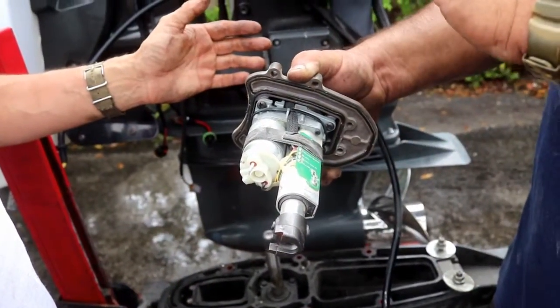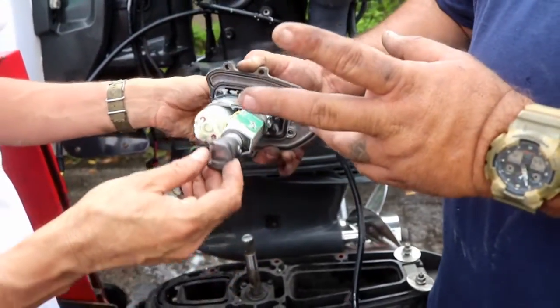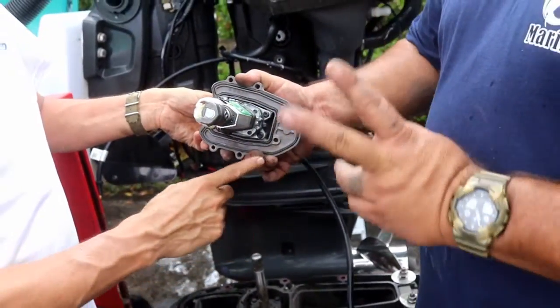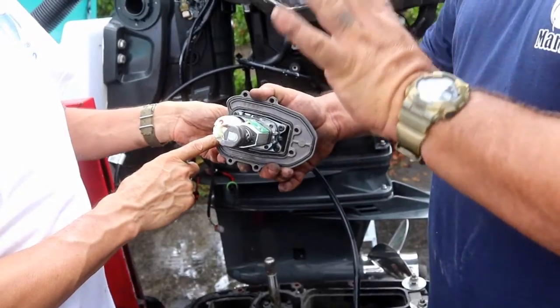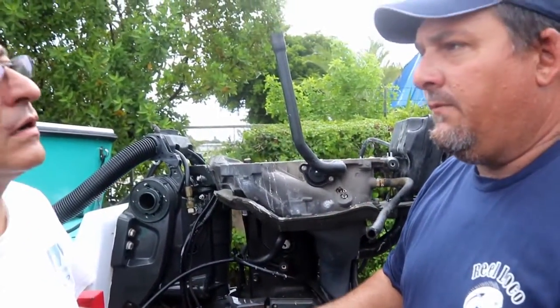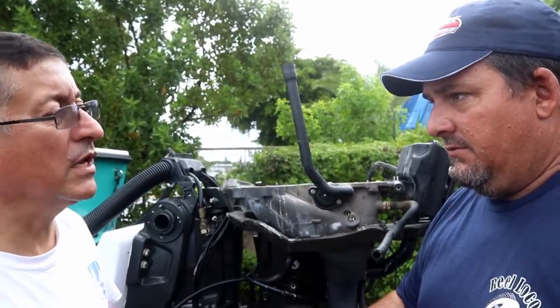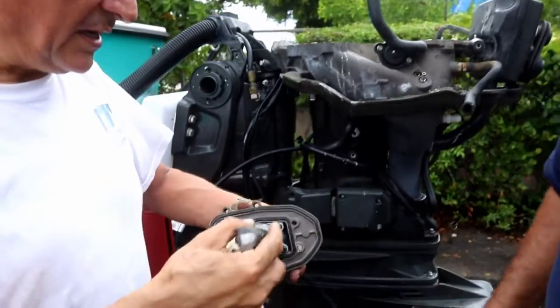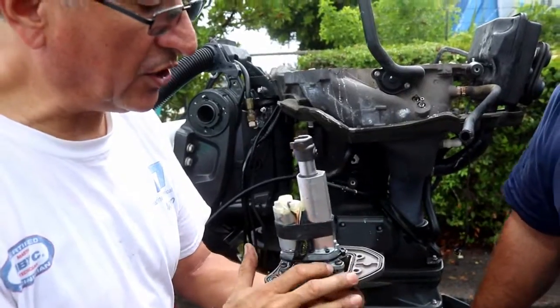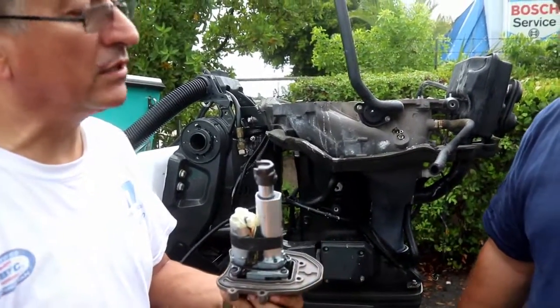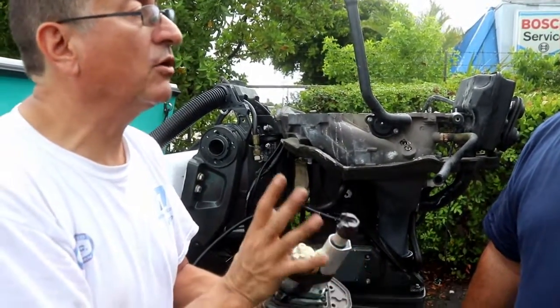On the system that controls all the electrical, there are two systems. You have two NMEA networks, a private network and a public network. The private network controls all the engine information, and the public network is basically the standard NMEA system. And that's the seal to keep humidity and water from getting in. This one should be completely dry.